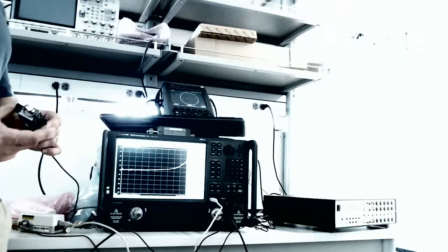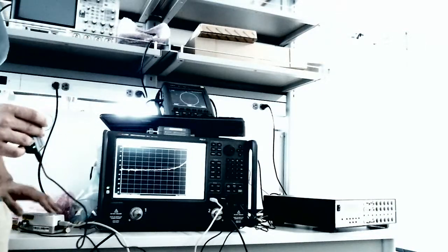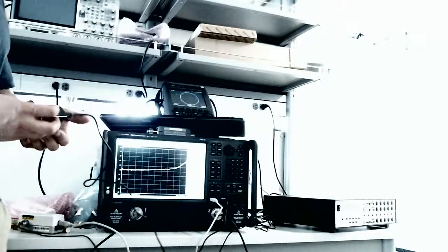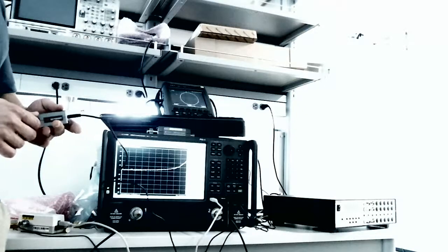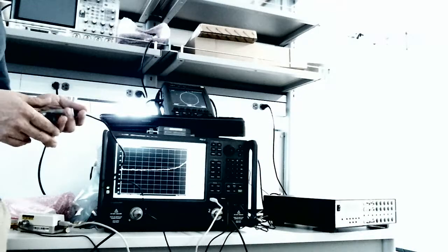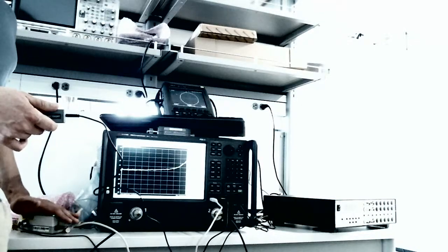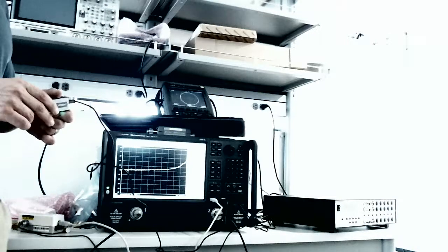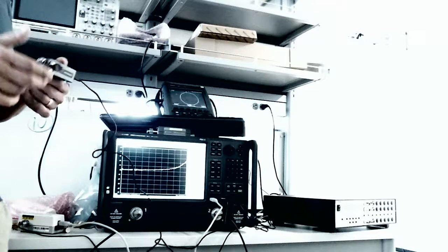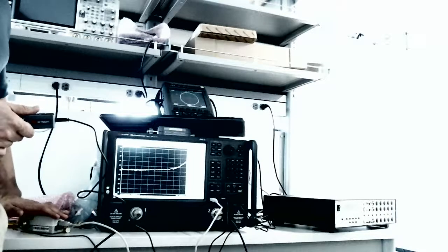This is designed in a way that it's for educational use, for manufacturing use. It's good, but it's not as good as this, right? And it's about a third or a quarter of the price of this. So that's why there's a difference here. So it's still, like I said, good. You're still going to be able to get accurate S-parameter measurements. It's just, for example, remember when I said you could get about 42, 47 dB of corrected values with this? With this, you're looking closer to 37, 39 dB of S11 directivity corrections, right? That's still a pretty good measurement in terms of the uncertainty. It's just not as good as what you're able to get with this.